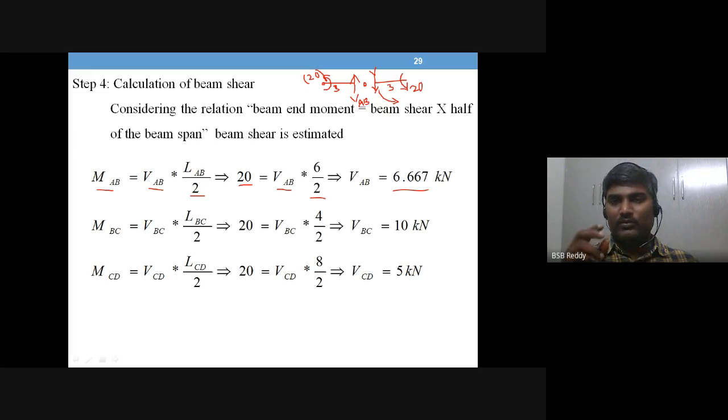Anyhow, when you take an element, again we talk about strength of materials, shear should exist with four arrows. Two are applied and two are the reciprocal action of the applied shear. We call them complementary shear. Right, it's all part of that subject. Okay, now we limit our discussion.